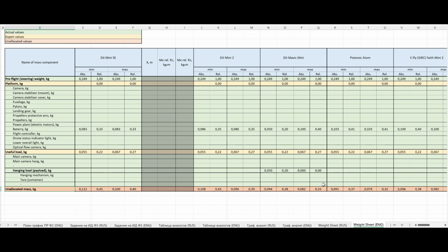angles, which is unfavorable, firstly when shooting video, and secondly when controlling a drone in confined spaces, at the moment of the non-floating start and the drone's position change in space. The pilot of an FPV drone loses orientation in space for a short period of time and may encounter an obstacle. In case of a change of the yaw angle, the quadcopter doesn't have such problems.